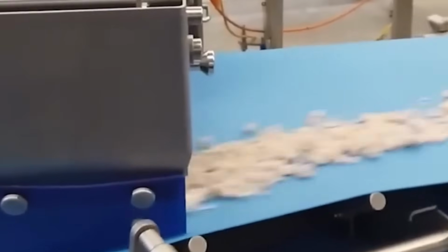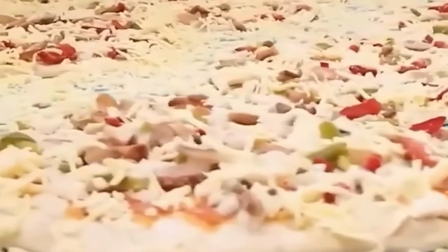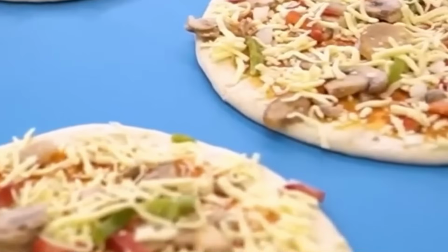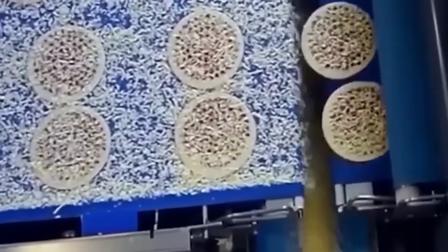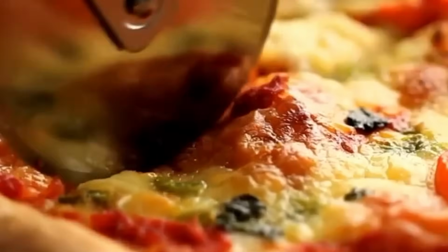Pepperoni slices are dispensed from a rotary carousel that places overlapping slices in concentric rings. Cooked sausage crumbles are metered through a hopper with a gate-controlled release. Vegetable toppings such as mushrooms, green peppers, and onions are added from separate hoppers using calibrated volumetric scoops. Bacon pieces and ham strips are dispensed from compartments lined with agitators to prevent bridging.